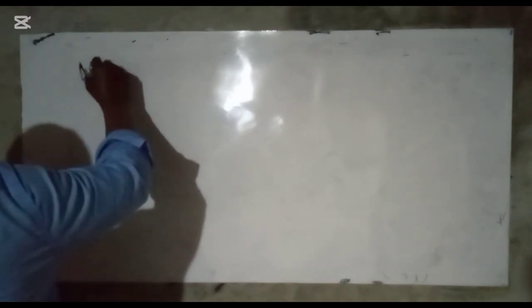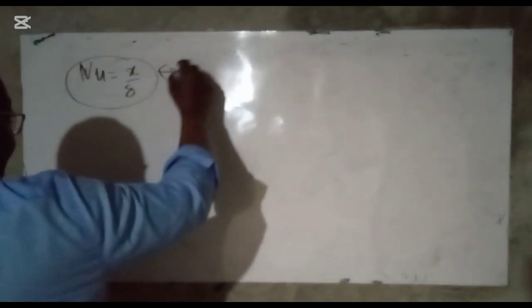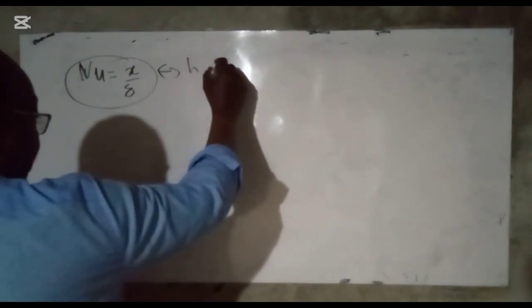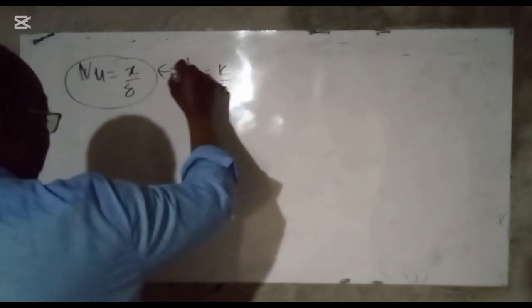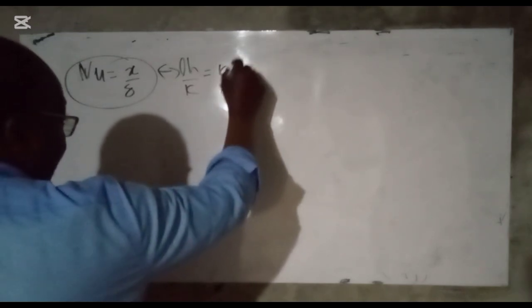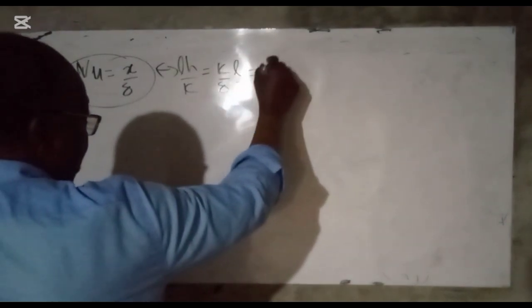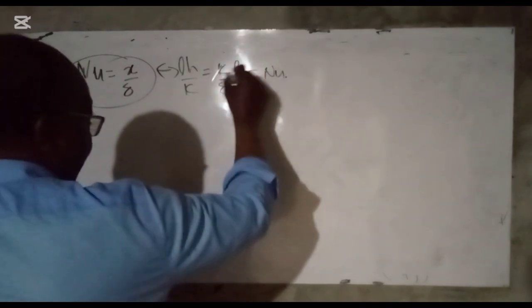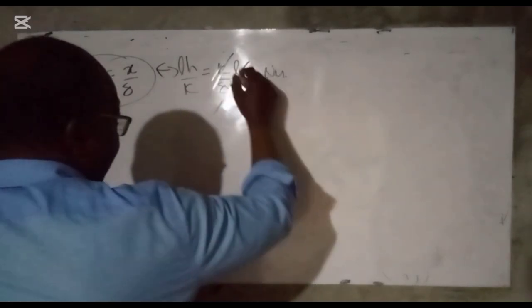that boundary layer. And we had said that the Nusselt number was x over sigma. And remember this, we simply got from the fact that we had h was k over sigma. So if we multiply by L over k, then that was the Nusselt number. So that cancelled. So we had L over sigma, and that L is x, is just a characteristic dimension.